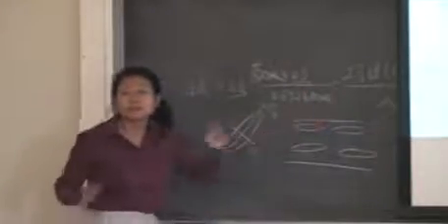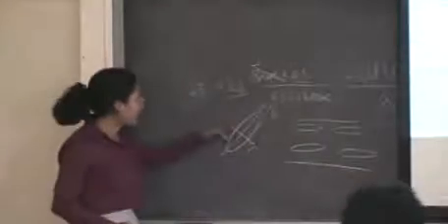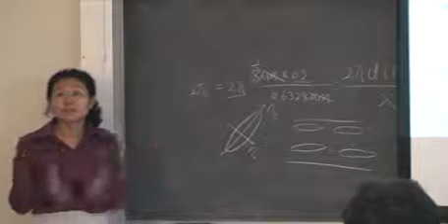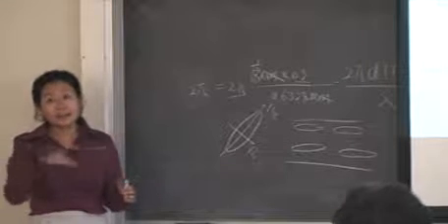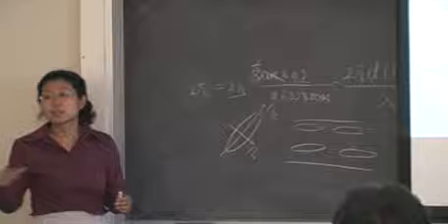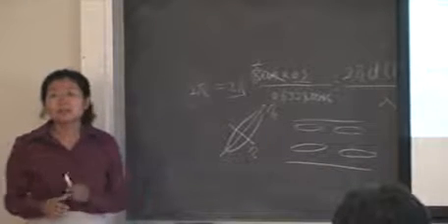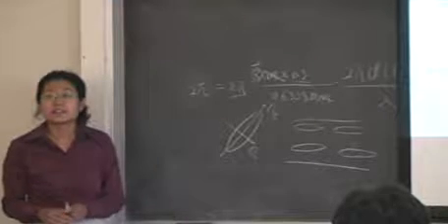The phase retardation comes from here. The beam is divided into two, and one passes along the long axis of the liquid crystal, another one passes through the short axis of the liquid crystal. So it has phase retardation, because all the liquid crystals align along the liquid crystal cell, right? You have a polyimide layer, you rub the polyimide layer, so it has a rubbing direction. Okay.